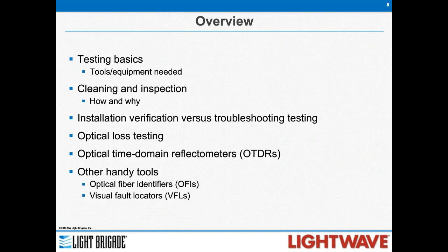So today, let's talk about today. We're doing testing best practices. We'll talk about some equipment needed, tools needed. Cleaning and inspection will be really where we start. That's got to be the beginning of every good testing session. Installation, verification, and troubleshooting testing. What are the differences? What are the different equipment needed? Optical loss testing, OTDRs, and a few other tools we'll cover at the end that would be good to have in your tool bag.